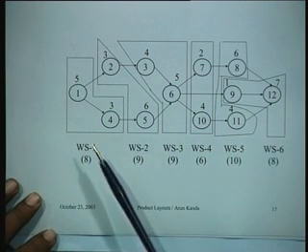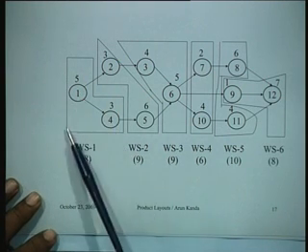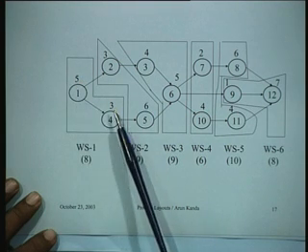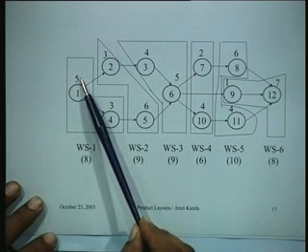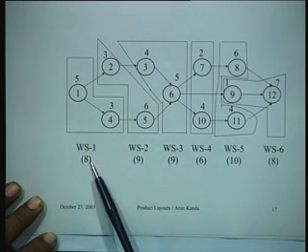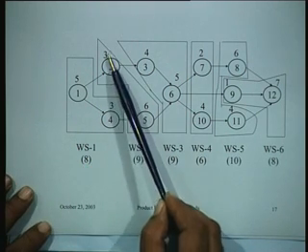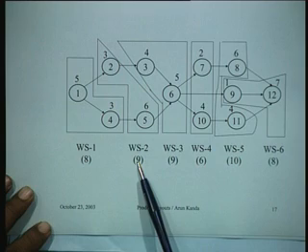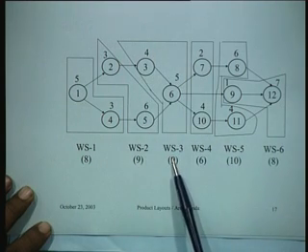What we can say is, I can club these two operations, 1 and 2, and this takes 5 plus 3, in whatever unit of time. So workstation 1 will take 8 units of time. I should not exceed 10, that's the important thing. So this is now 3 and 6, which takes a time of 9. This one takes 4 plus 5, which is 9.